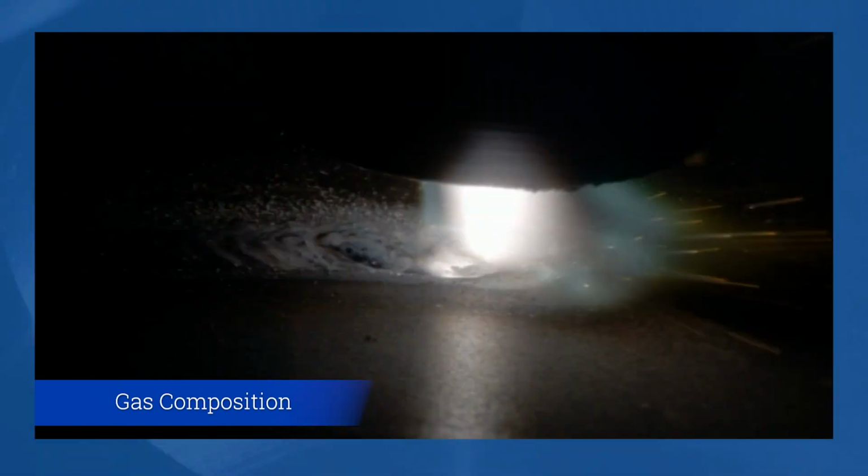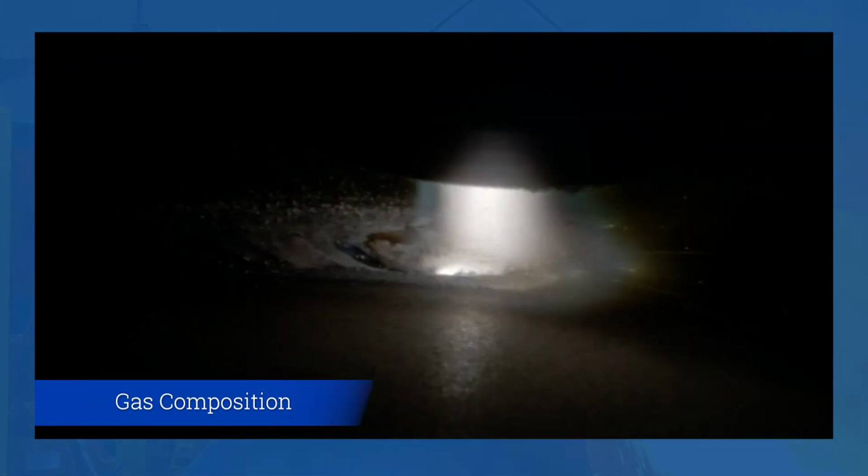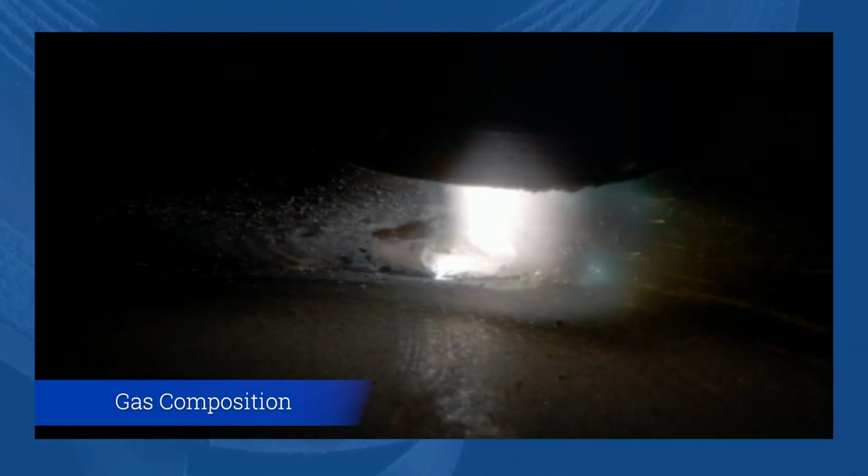The advantage of this is there's always oxides present in a weld, and you have to reduce them somehow or another, because the melting point of an oxide is much higher than that of a base material. So you either reduce the oxides, that's get rid of the oxygen, or you throw too much heat at it to try to melt the oxides.